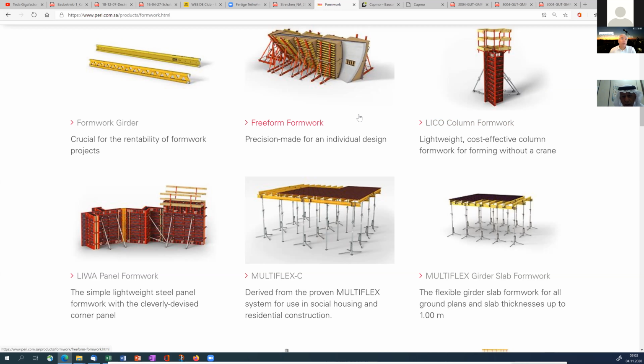So the conclusion really is to save the timber and the wood, but still we will have it also in this flexible deck formwork, but to save the timber, because this is also expensive. I can imagine in Saudi Arabia, timber is not so easy to get. And after using it on the structure, you have to get rid of the wood. So that's the reason why they use more and more the systems, like you see here.